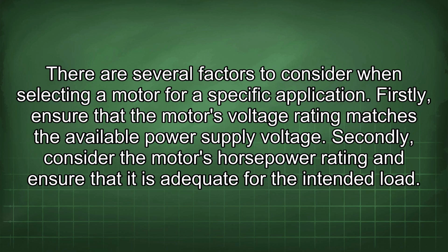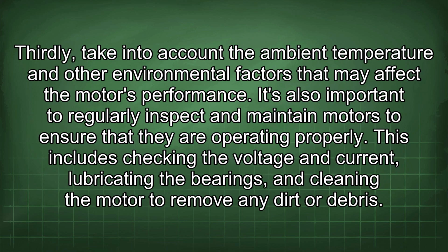There are several factors to consider when selecting a motor for a specific application. Firstly, ensure that the motor's voltage rating matches the available power supply voltage. Secondly, consider the motor's horsepower rating and ensure that it is adequate for the intended load. Thirdly, take into account the ambient temperature and other environmental factors that may affect the motor's performance.